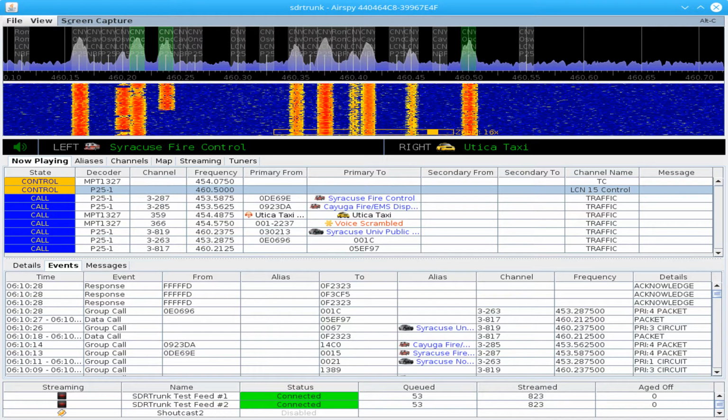There are many software applications available in the open domain that are useful for decoding radio signals from IQ samples provided over USB. SDR Trunk has the decoders we want and is designed for the use of trunk signals. The application is Java-based and can be easily transferred to any OS running Java. SDR Trunk can simultaneously decode all channels within the tunable bandwidth of the ADRV9002, or can be configured to automatically create and tune individual traffic channels when decoding the control channel.